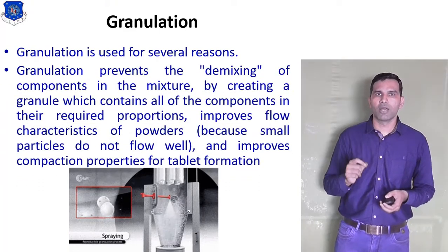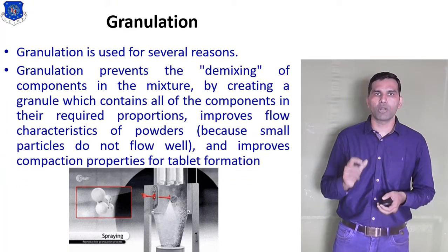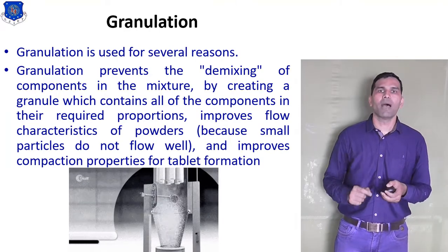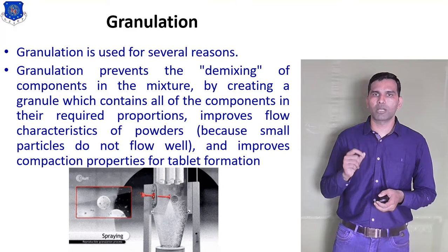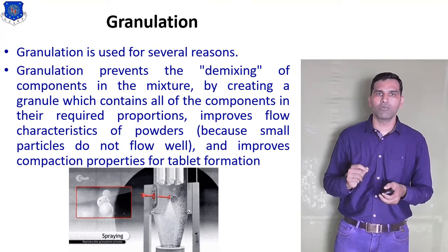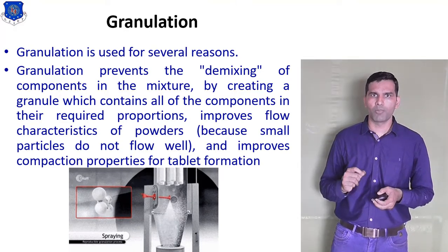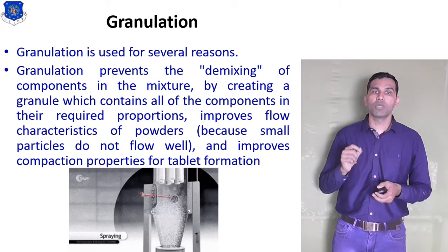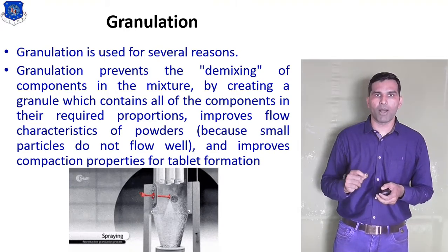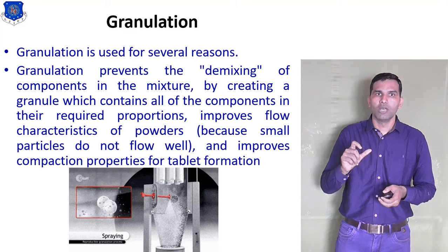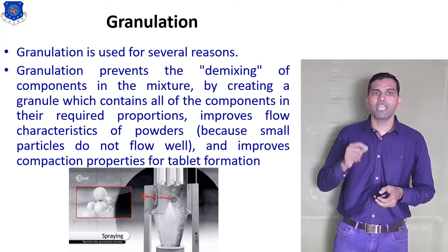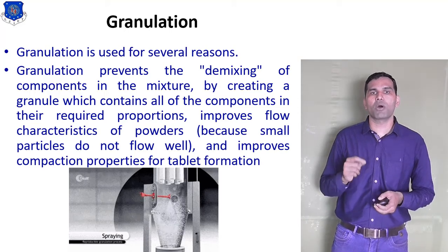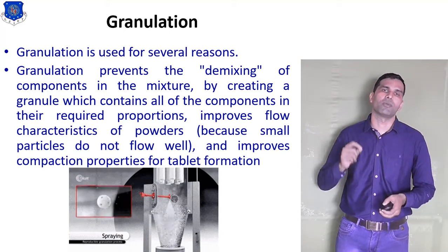Granulation prevents the demixing of components in a mixture by creating a granule which contains all of the components in their required proportions, improves the flow characteristic of the powder because small particles do not flow well, and improves the compression property for tablet formation.